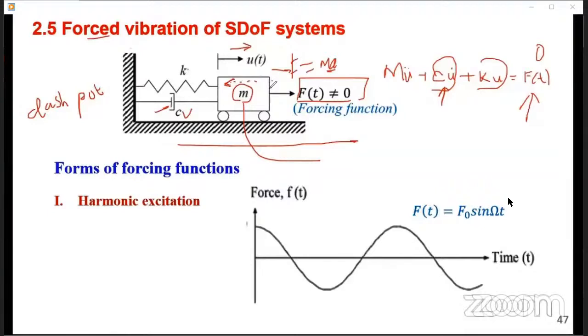And that's why D'Alembert stated, from Newton's second law, that a system may be set in a state of dynamic equilibrium by adding to the external force a fictitious force, fictional, not real, which is commonly known as the inertial force. This could be important, maybe you could note it somewhere, because it's a statement of D'Alembert's principle. I don't know whether I made that statement before in lecture 2.